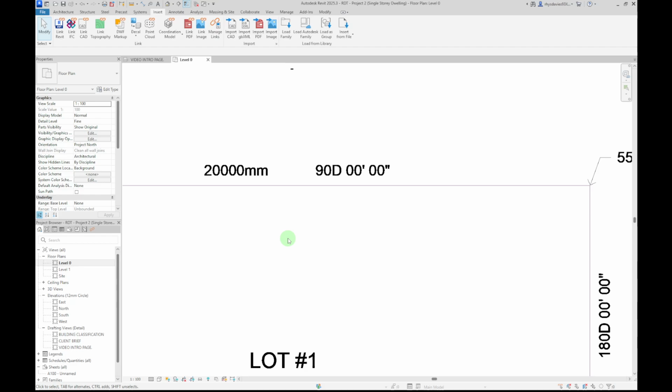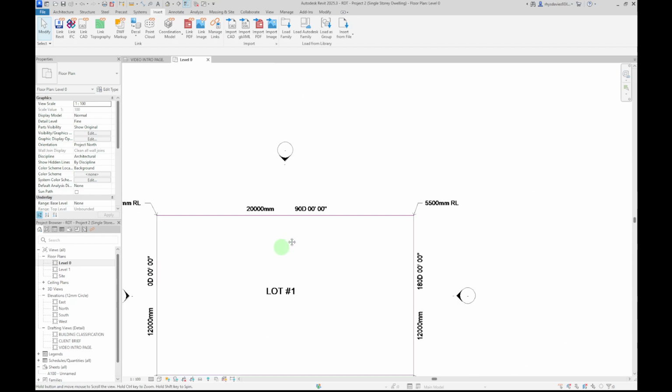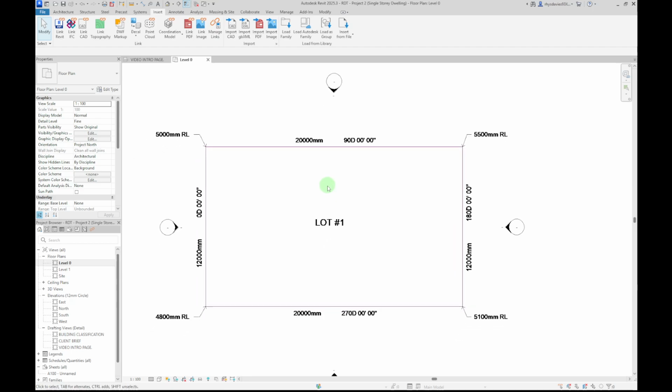That means Revit has picked up the units of the original AutoCAD file correctly, and I don't need to change anything. So that's a really positive aspect. With more complex files, and especially if you bring in DWG files from other software or other providers, this may not work initially, and I'll try and set up a lesson which shows what to do there.